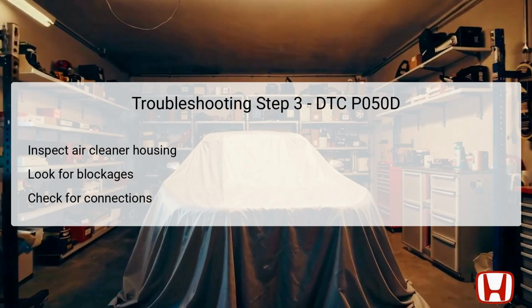However, if the inspection reveals issues, the air cleaner housing may need to be replaced to maintain proper air filtration and engine performance. The fourth step focuses on the air cleaner element's condition. This component must be free of dirt and debris to allow unobstructed airflow to the engine. A dirty air cleaner element can significantly detract from engine performance and negatively influence idle behavior during cold starts.